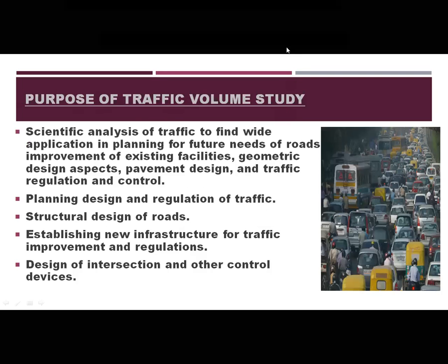So what is the purpose of collecting this data, or of a traffic volume study? First one is scientific analysis, and by scientific analysis we could work on the improvement of existing facilities: geometric design aspect, pavement design, traffic regulation and control devices.